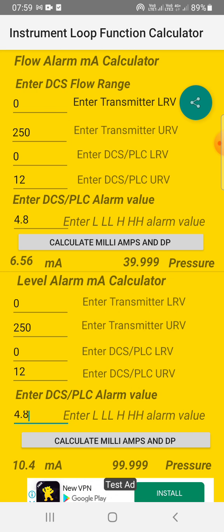And if it's an FF transmitter, or if you want to simulate using a hand pump or digital pressure calibrator, you have to apply 99.999, or you can say 100 mbar pressure to get the level.